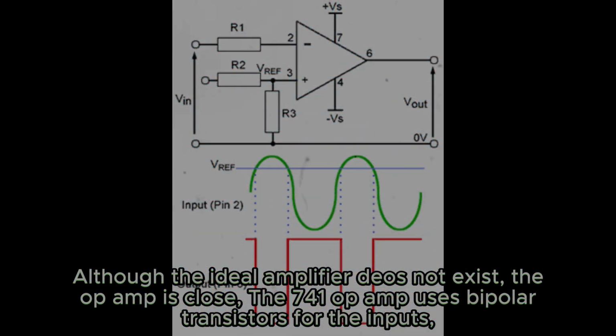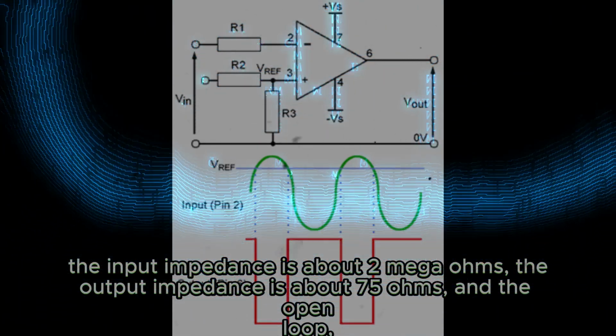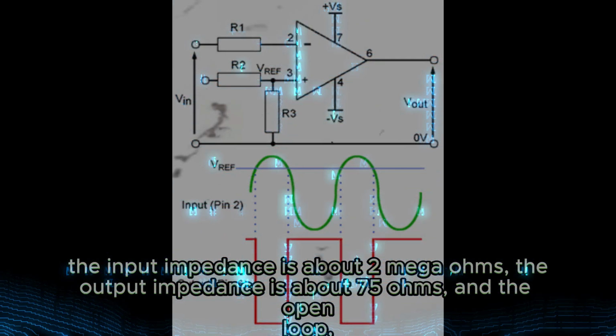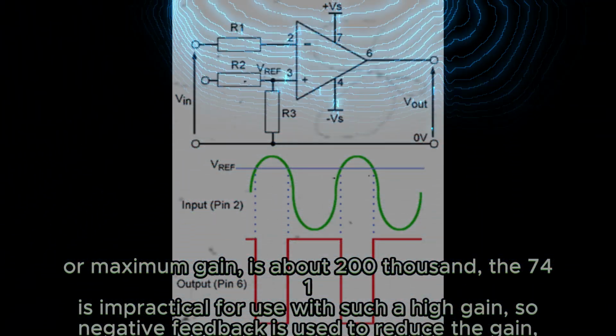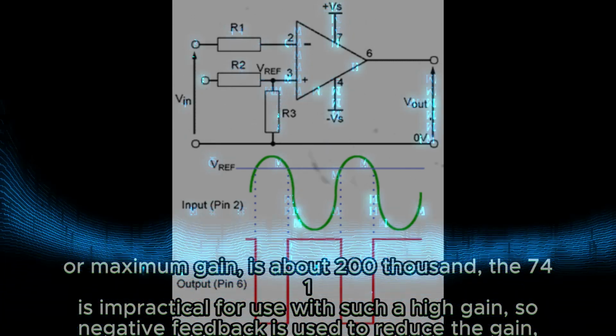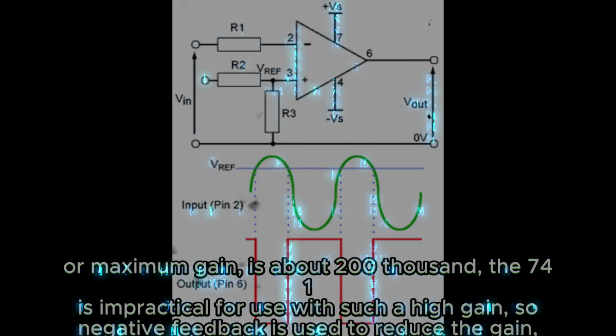The 741 op-amp uses bipolar transistors for the inputs. The input impedance is about 2 megaohms, the output impedance is about 75 ohms, and the open loop, or maximum gain, is about 200,000. The 741 is impractical for use with such a high gain, so negative feedback is used to reduce the gain.